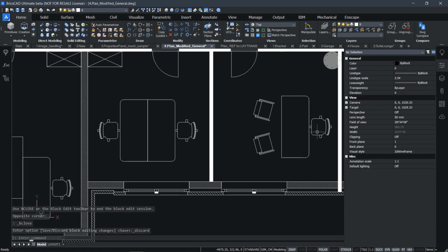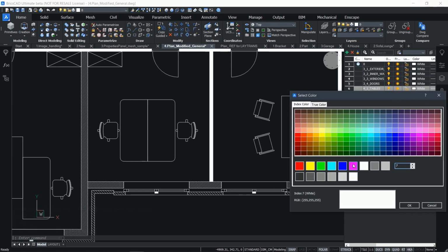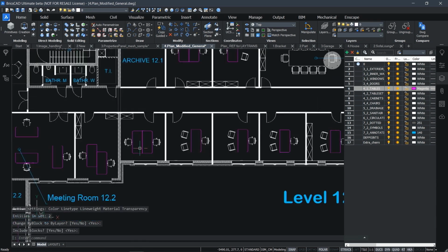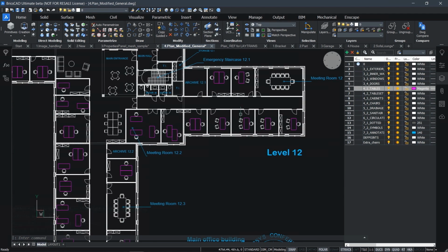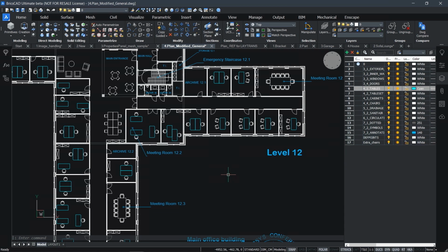It's a mistake I often make, and I'm sure other people do as well. So instead of changing it by block, we change just the color of the layer, and then we use the new command, set by layer, to change everything on that layer in one go. We did the color here, but it can be, of course, any other property of the layer.